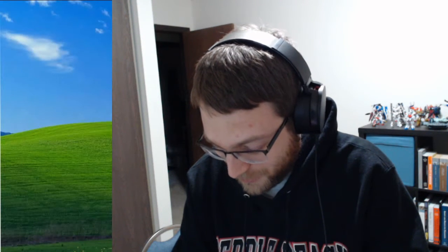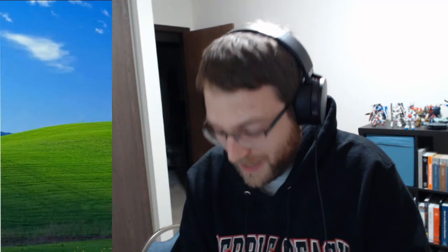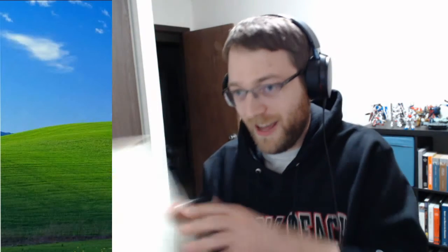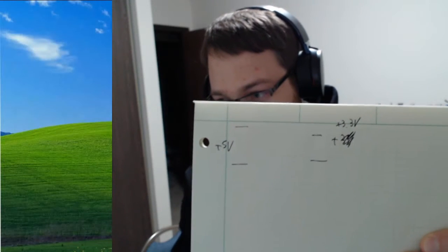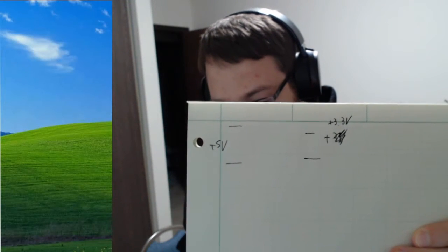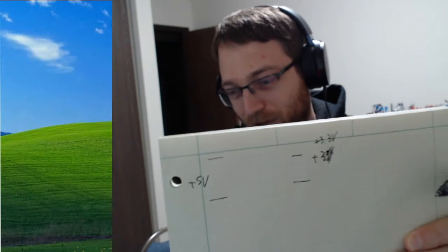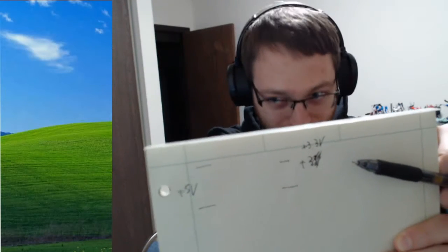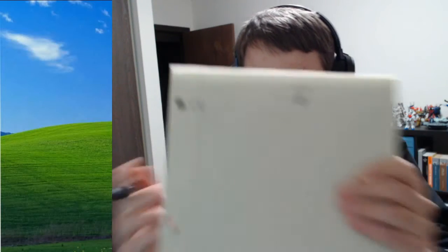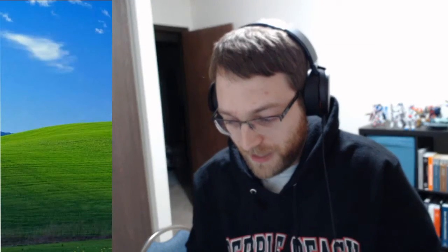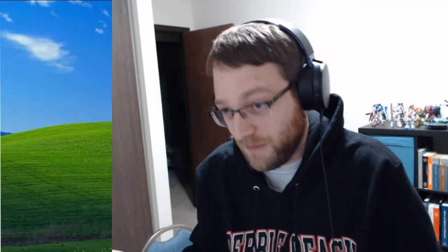Do I want plus 3 volts? I want plus 3.3 volts. Okay, so a standard thing that'll happen is you'll have your two sections of the line. You'll have a 3.3 volt load that you need to supply, and you'll have your 5 volt power supply coming off the other side here. A lot of times when things run off USB or when they run microcontrollers, they need 5 volts.